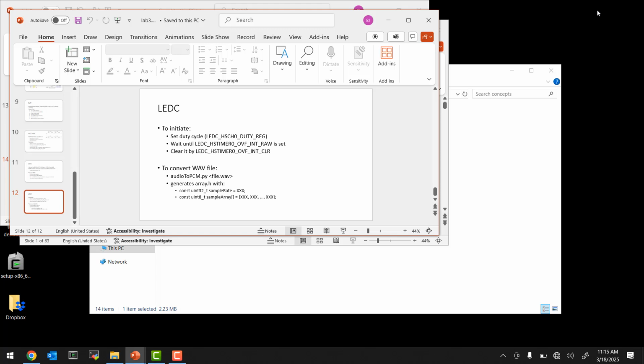I was thinking to make a level meter where you take the audio amplitude and you use it to light up a certain number of LEDs depending on the amplitude of the audio. Additionally, you can color code them to indicate the level as well. The more LEDs that are lit up, the more red they'll be. I didn't use HSL, I used one called Fire.